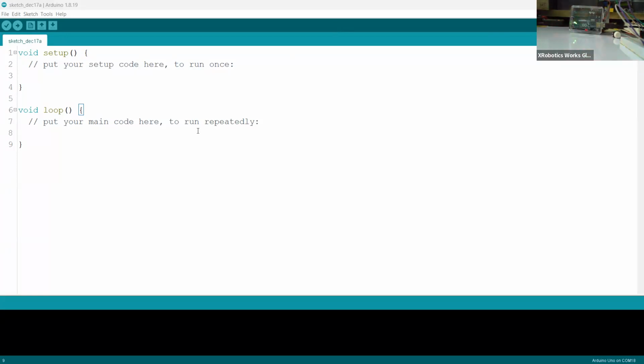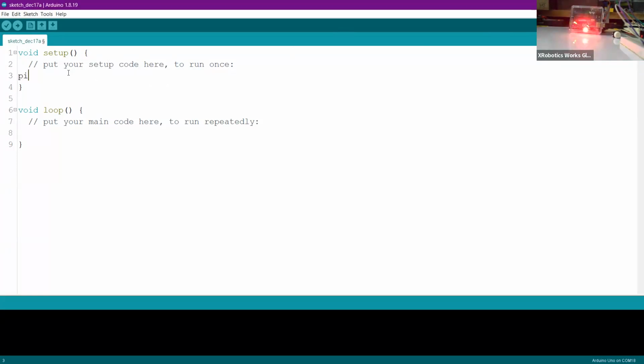So now if you look closely, the LED is blinking. Under this setup program, what I asked you to write earlier is the pin mode. And why write the pin mode? Because we have to address individual pins. Individual pins means what? Suppose we are focusing on taking input from any of the pins, or producing output to any of the pins, we must acknowledge those conditions to our board first, and only then will our board understand that this particular input device is connected with our board.